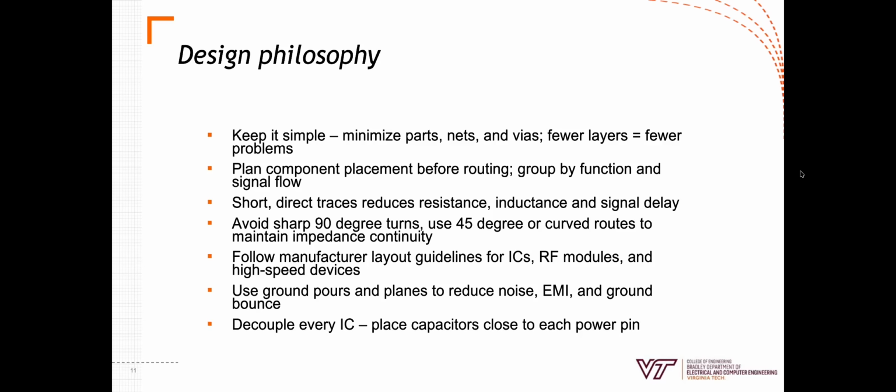So these are just some design philosophies that I've learned making PCBs over the years. Keep it simple. Try to minimize the amount of parts you need and passive components to keep your board footprint small. We want traces as short as possible and as few vias as possible, and try to use the minimal amount of layers possible.